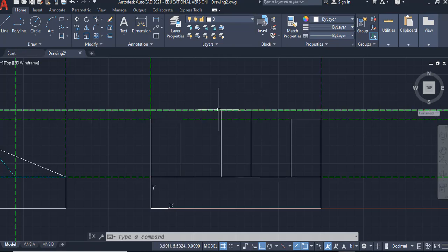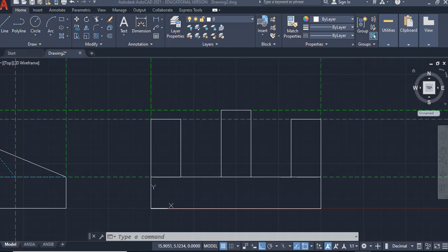And we could figure out the XY coordinates for all of this, but if you use snap, copy, move, those kinds of modify tools are going to save you a lot of time, because a lot of objects have very similar symmetrical repeated shapes to them. So really get used to using these modify tools as well as the XY coordinates for all of this stuff.